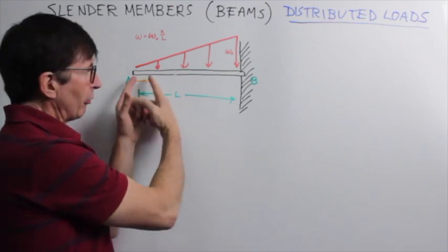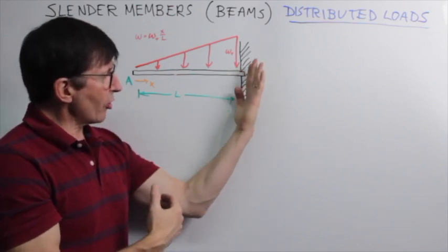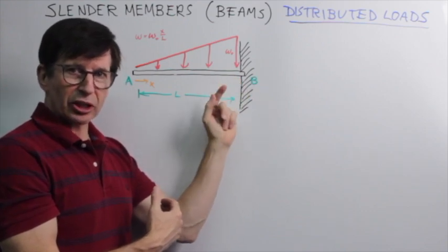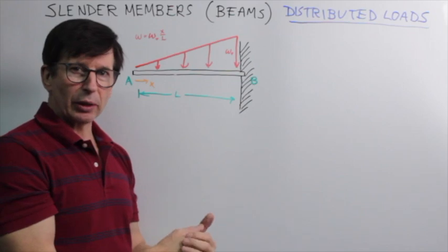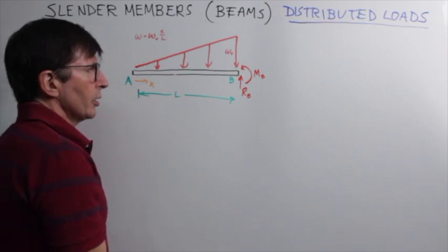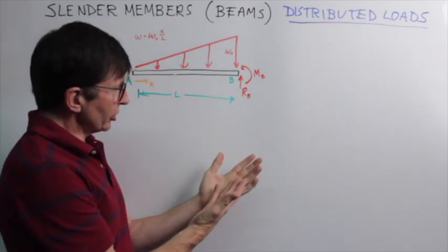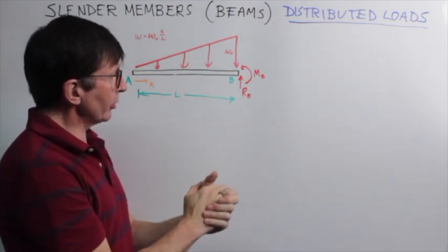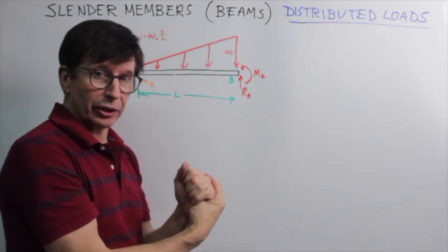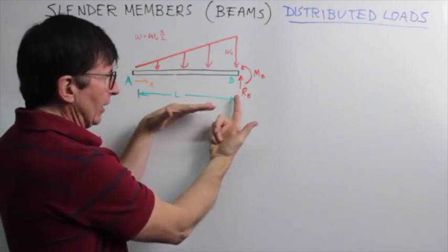And so our free body diagram is just going to be the beam itself, and we need to replace the wall with the reaction, shear force, and moment that the wall is exerting on the beam to keep this thing in equilibrium. So if we remove the wall, draw that free body diagram. So we replace the wall with the reaction at point B, which is drawn in the positive coordinate direction, and we can tell from our intuition that that is going to be the direction that the load will be applied to counteract all of this pressure hanging on the beam.